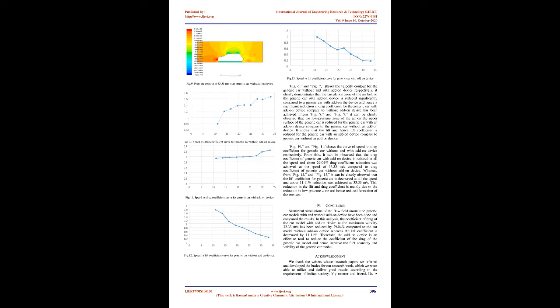In the present research, the pressure-based solver is used because it has recently been modified and extended to solve for viscous flow. Also, this project requires surface pressure, so the lift and drag forces acting on the models can be calculated accurately using the pressure-based solution. The solution setup details are listed in Table 4. 3. Results and discussion.